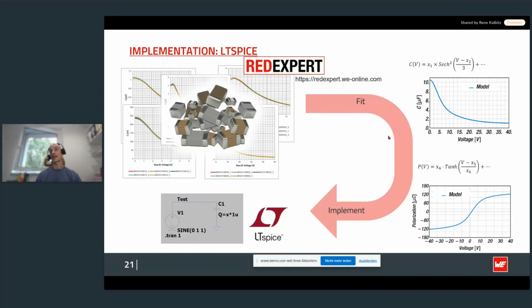This step is required since LTspice needs the charge equation, which is the polarization. The model actually was designed from the very beginning so that its charge equation uses only trigonometric functions available in LTspice. We do not have the time to speak more about this technicality, but the fact that the analytical integral of the capacitive model only contains simple trigonometric functions is an important feature of the model, actually.